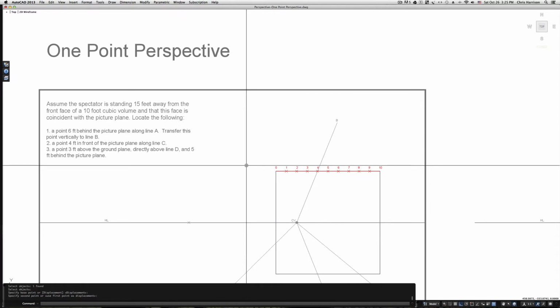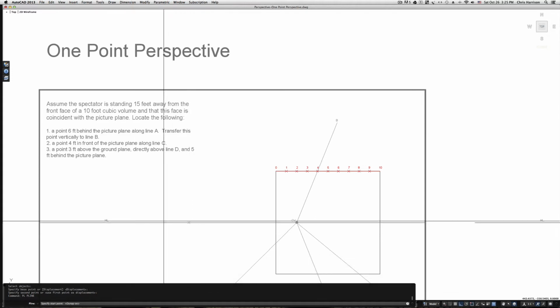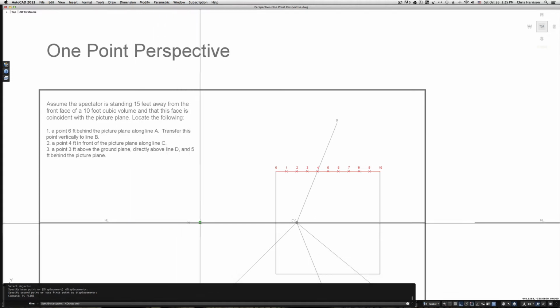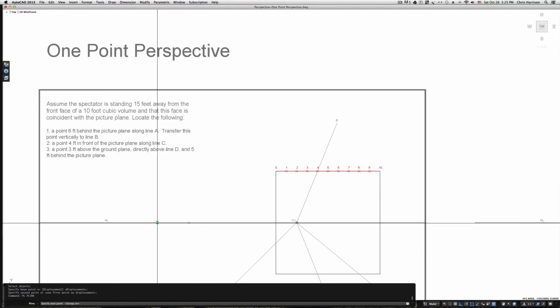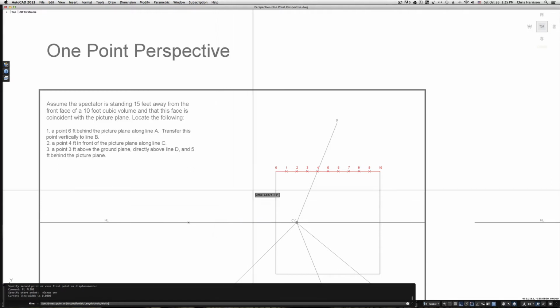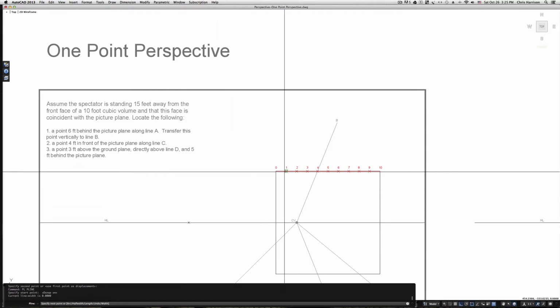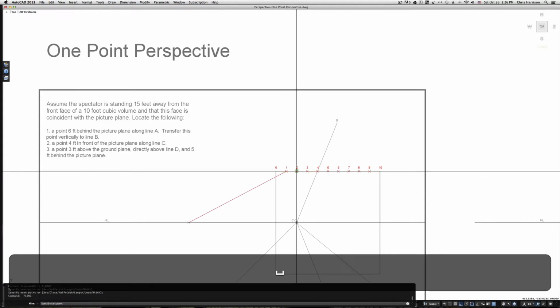The next thing that we have to do is to create a diagonal point, and I've placed my point here. It doesn't matter where you place your point. It will change the look of the perspective depending on the location on the horizon line that the point is placed, but for mine I'm putting it here. The next thing we want to do is then run this from this diagonal point to each of the 1 foot breaks in the 10-foot line. So I'm just going to do that.